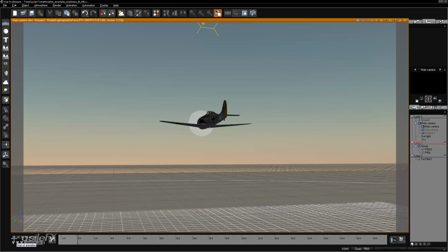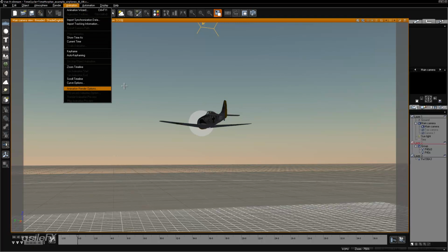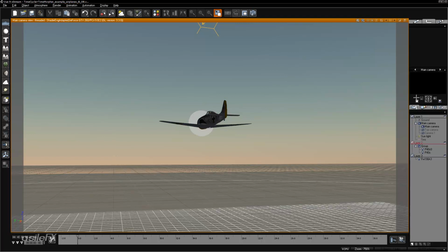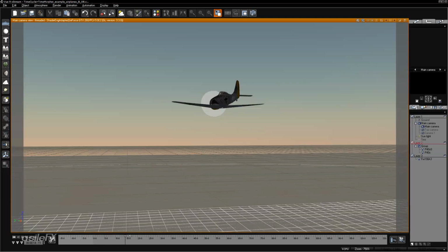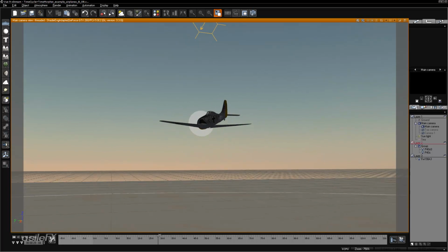And if we were to go ahead and render this out, at the moment everything is dynamically linked. So even though we have animation when we scrub the timeline, we don't have the ability to play an animation or even access the render options. So we do need an object that is going to represent the amount of time we need in our animation. I typically just like to use a null object and add a position keyframe in order to make sure it's not interfering with any of the graph connections.